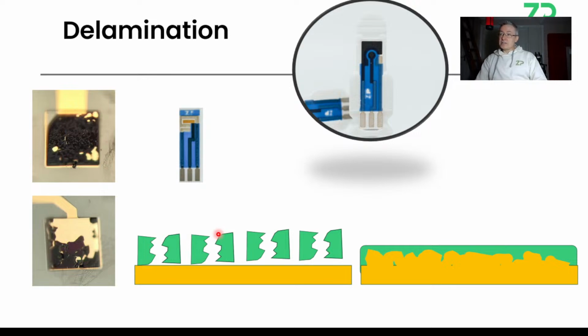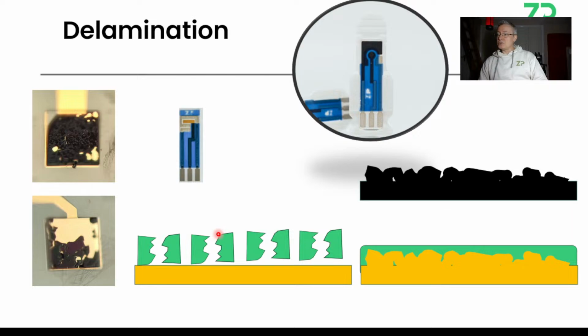Whilst making this slide, I realized that for what they're doing, they might as well just use carbon. They didn't have to use gold. Sometimes people use gold because there's a precedent in the literature for it. They're probably following papers from University of California San Diego, and they tend to use a lot of gold, but carbon would do the job just as well, and they'd probably have better adherence between PEDOT and carbon. Carbon's rough, and there's also a chance for pi-pi interactions, so you may get a stronger binding to carbon.